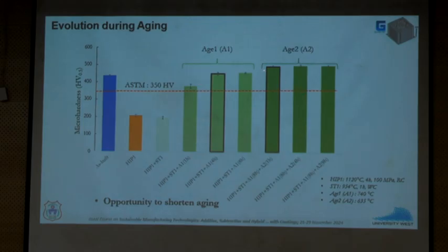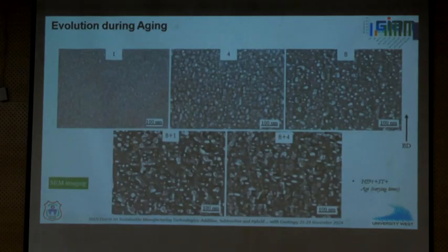Here you have achieved this right after 1 hour, so can you stop it after 1 hour? So, can you convert your two-step aging from 8 plus 8 hours to 4 plus 1 hour and shrink that, because that is a substantial reduction if you can go from 18 or 20 hours to 5 hours.